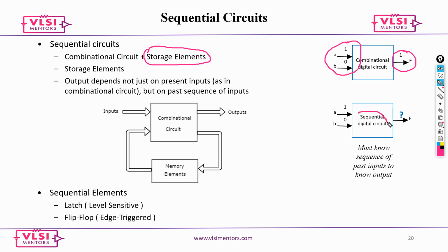So sequential circuits means your combinational circuits plus your storage element. And remember, your output does not depend only on your present inputs, it also depends on a past sequence of inputs. That is the main reason why we call these storage elements.